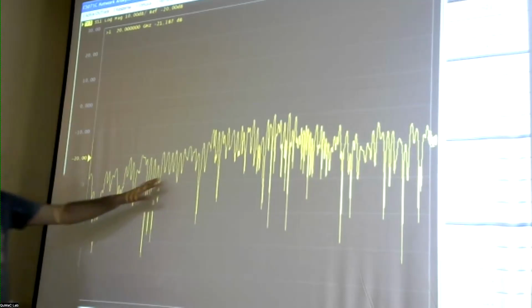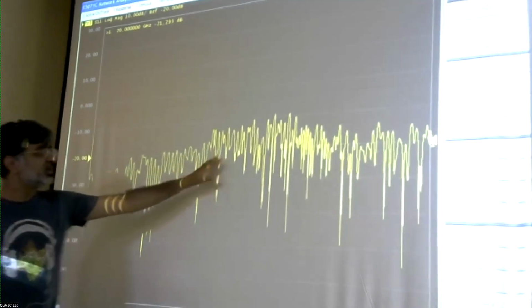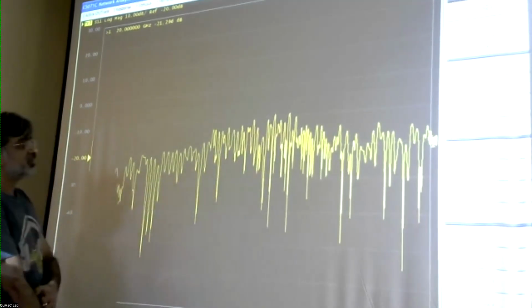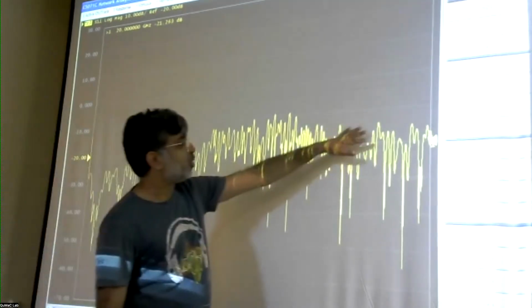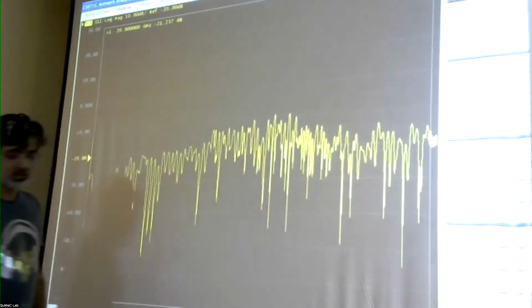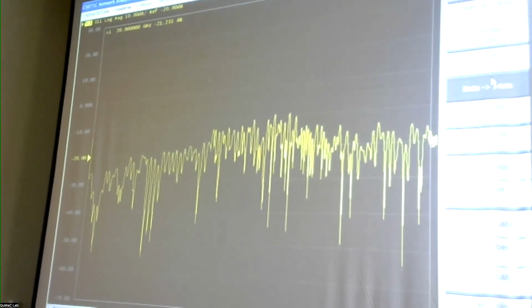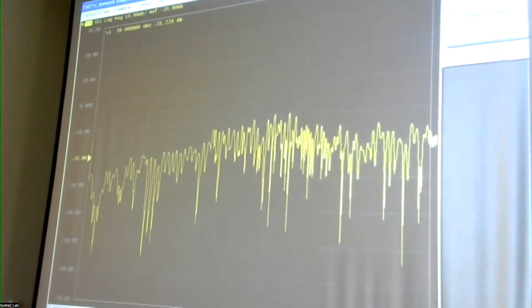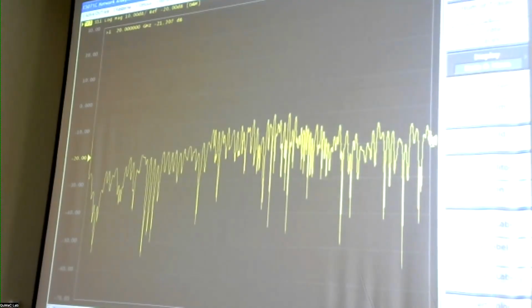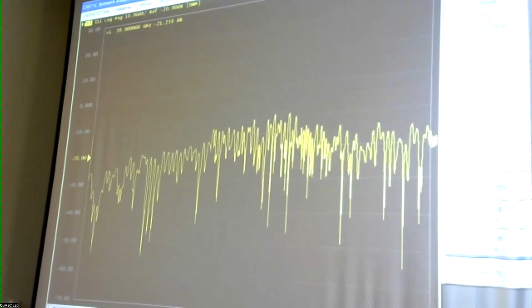So this cable is decent up to about 10 gigahertz, not so great after that, even though here it seems to be around, the mean is around minus 20 dB. You can look at it from the other side. So if I go to S22, let me actually put this to memory, and we can also display the memory trace along with the actual trace.